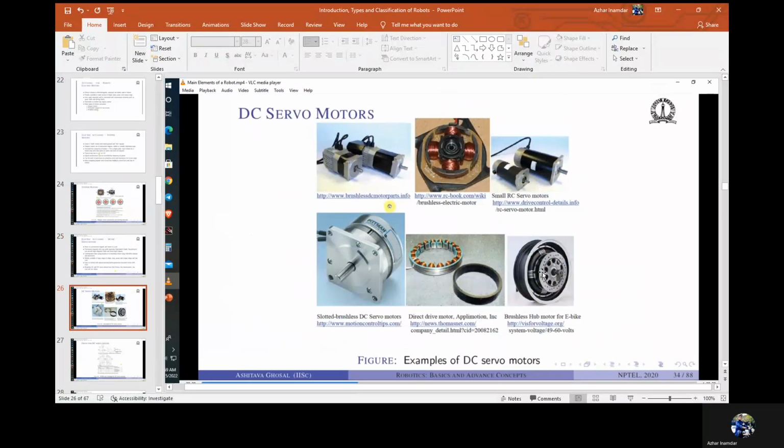So in an electric bike, we can invert it. The stator is inside and the rotor is outside. We provide current to the stator, and the rotor, which has the wheel mounted on it, will rotate. This is the basic mechanism of a hub motor. As you can see, it looks like a hub, and we can mount the wheel on top of this. When you provide current to the stator, the rotor, which is outside, will rotate.